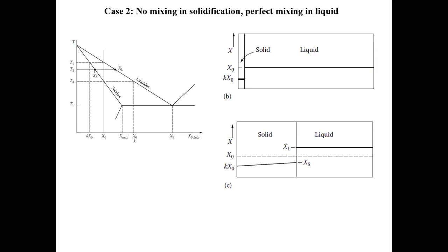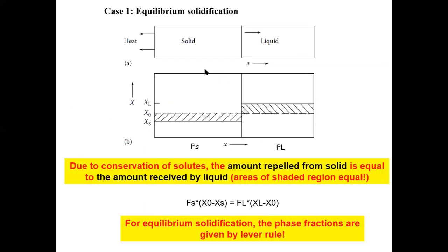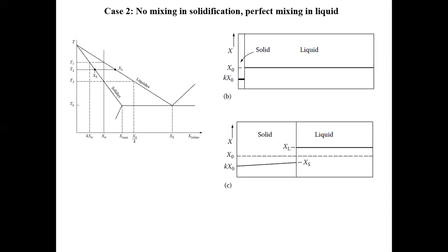And if you lower the temperature, you require that after you lower the temperature, the solids composition, the solutes within the solid, also redistribute themselves to achieve this perfectly uniform distribution. You're going to wait for a very long time, right? And if we cannot afford that time, what is going to be the consequence?